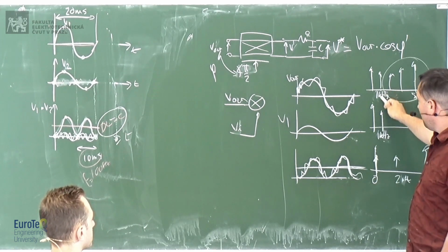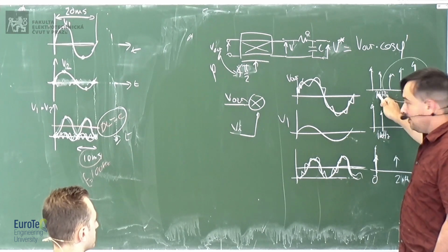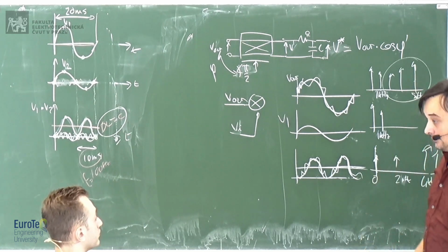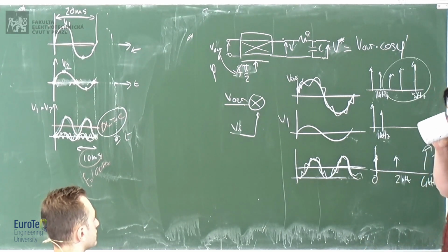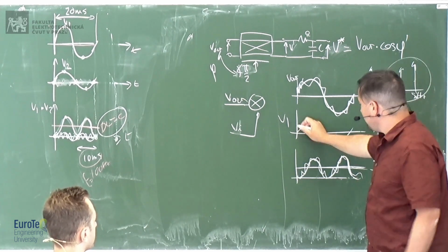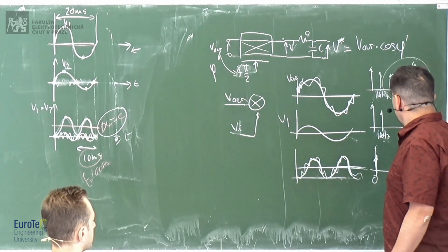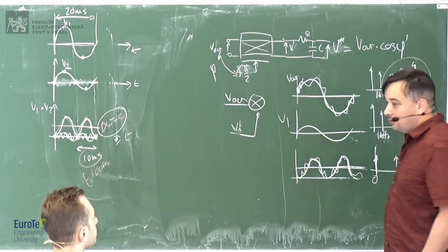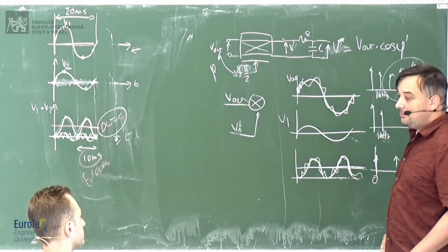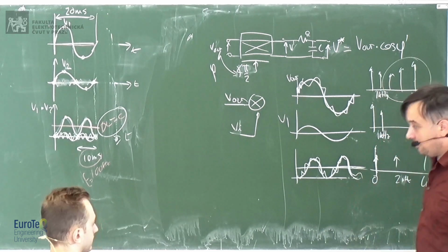The first harmonic, because it's the only case when you have a difference of the two frequencies which gives you 0. Yes, okay? So unless there's also noise in the input. If Vn had noise, of course, then there would be something else. If you have by accident 5 kilohertz here, then you will have also 0. But if you have a very nice pure sine wave at the input, this method allows you to erase all the disturbances.